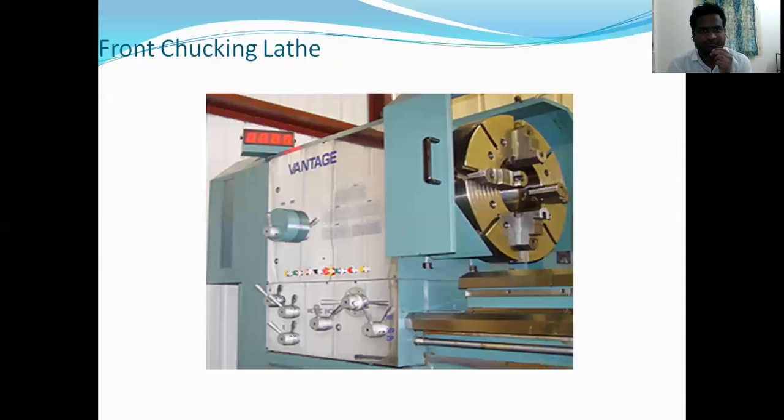This is the front chucking lathe. We already know there are five types of chucks: 3-jaw universal chuck, 4-jaw independent chuck, magnetic chuck, drill chuck, and mandrel chuck. These chucks are also known as work holding devices. Based on the chuck, we call this a chuck lathe, and it is suitable for short workpieces, small workpieces in small numbers.